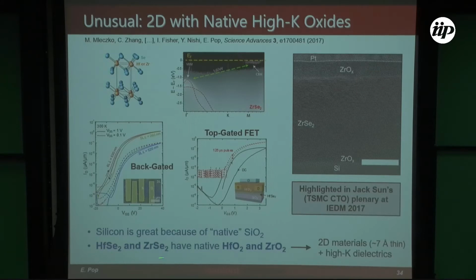So these two layered semiconductors, hafnium selenide and zirconium selenide, oxidize very easily, maybe too easily, into hafnium oxide and zirconium oxide respectively, right? And here's a TEM cross-section image of a thick chunk of zirconium selenide that was transferred onto silicon and capped with platinum, and before the capping happened, the top layer is already oxidized into some zirconium suboxide, right? It's very clear that it does that. This is just ambient oxidation, and that's probably just ambient oxidation too.